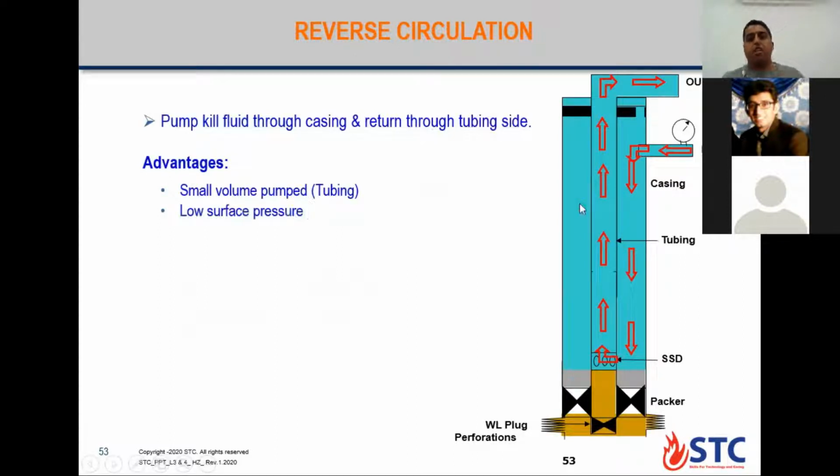In this case, the completion brine already filled the annulus area from the beginning. When the kill fluid enters the capacity of the pipe, you will have killed the well already, but you need to continue. The kill fluid replaces the original gas inside the string and the original completion brine inside the annulus.